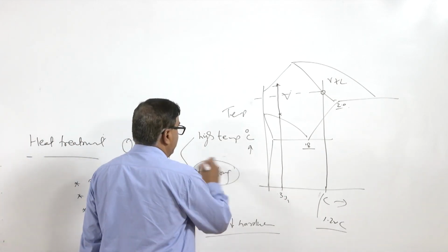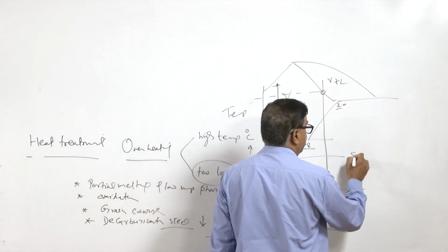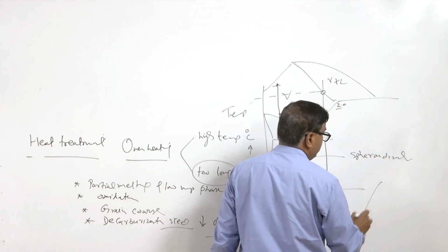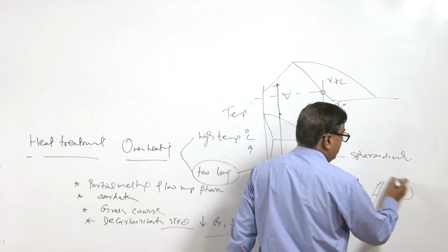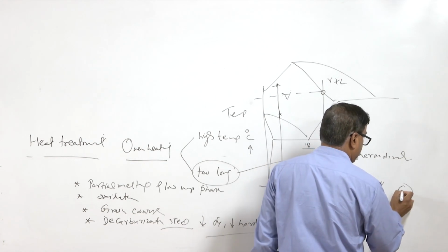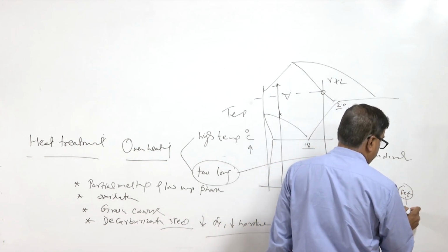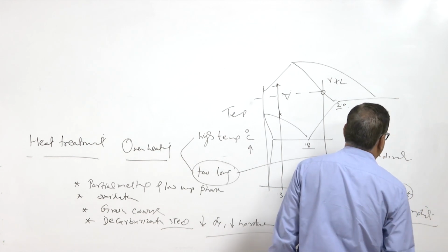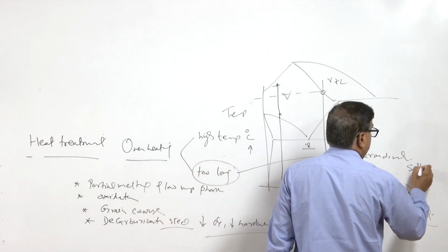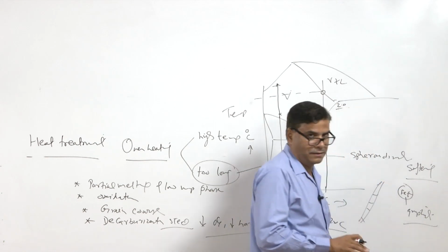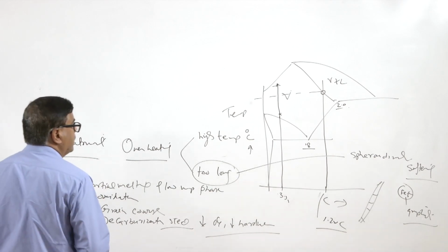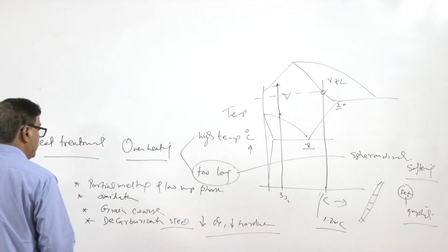Similarly, prolonged heating also causes spheroidization, especially in the case of steel. Spheroidization is basically the cementite plates getting spheroidized, forming nodules and spherical-shaped particles of again Fe3C, or sometimes graphite also, leaving the iron in the matrix. Basically this leads to softening of the steel and reduction in mechanical properties in terms of tensile strength and hardness. So, unnecessary prolonged heating is also not good, and if that happens inadvertently, unknowingly, then these undesirable